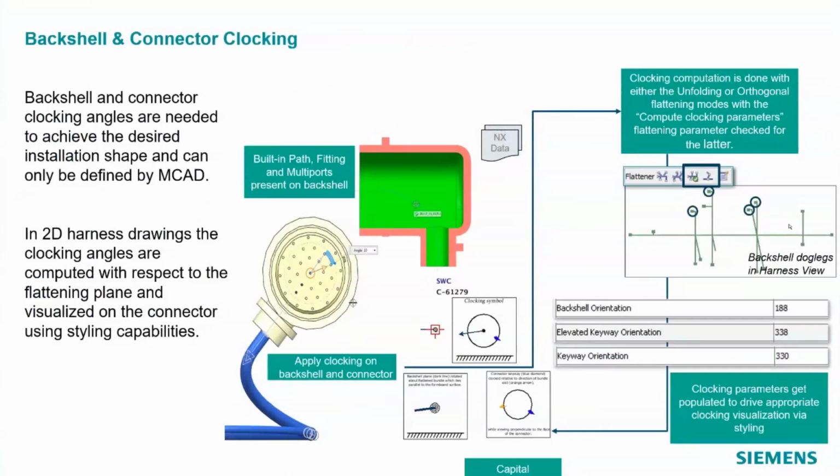Backshell and connector clocking angles are needed to achieve the desired installation shape and can only be defined by MCAD. So representation of these angles on harness drawings is crucial for harness fabrication. We now have NX extended integrations to support connector and backshell clocking.